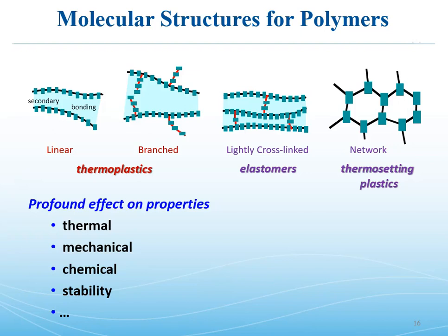Chemical properties, the stronger the bonds that are already there, the less likely that you are to want to bond to something else. That's effectively the foundation of chemical stability. So the more covalent bonds you have, generally the more chemically stable you are. And then stability, that last one, beyond chemical, would include things like weathering and most specifically ultraviolet and photolysis and photooxidation resistance.